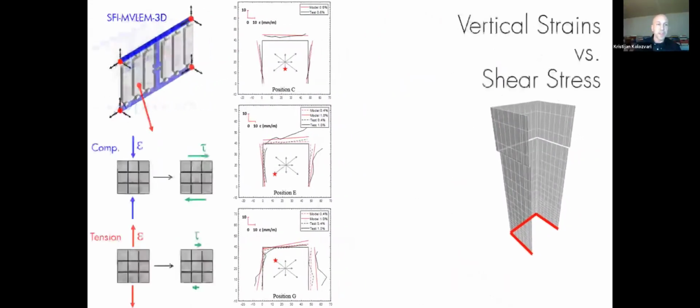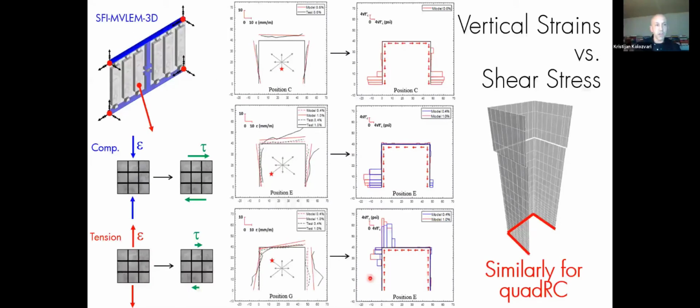Now, another thing that's also interesting, talking about the shear flexure interaction model, and similarly for the finite element model, this is really demonstrating interaction between axial and shear response at the level of each of these panels. So if you have a panel that is principally in compression, that one is going to resist more shear, right? Versus when you have a panel that is in tension, which essentially opens the cracks in concrete, you can't really transfer a lot of shear, or in some cases very little.